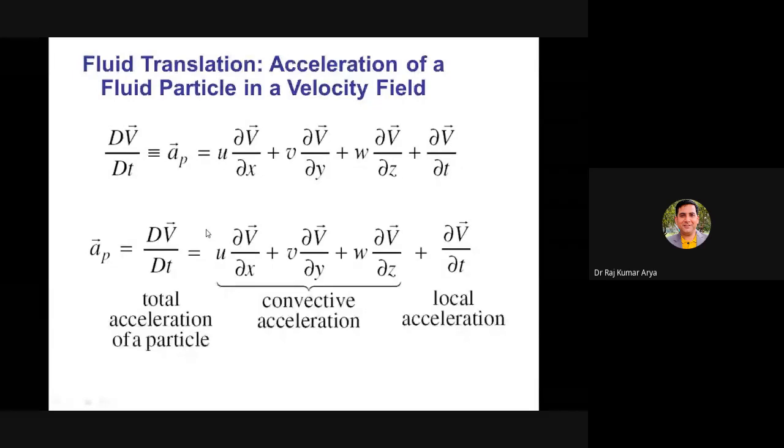Once you calculated that, after that you calculated the acceleration of fluid particles at a particular location. This is also an important point in case of flow of fluids in a pipeline or in some area. There you are also interested in what the acceleration is here, because acceleration will provide the force, and then you can calculate the pressure force available there or the velocity field.